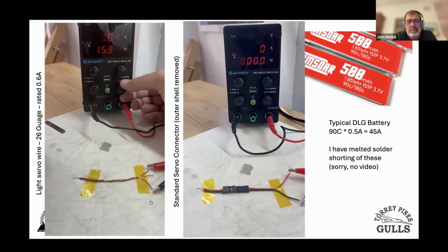Okay, so note my little chart. You probably noticed this is not picking on Armstor. We're almost all flying these gumstick batteries, and they're really good batteries. They're tiny. They have a lot of capacity. They have a 90C current rating, which, do I believe that for running an electric motor? I don't know. I tell you what I do believe it for, that if you short it out, it'll give you 45 amps. So that was 10 amps on the left. If you had a shorted connection with one of these little batteries, you would well exceed 10 amps.